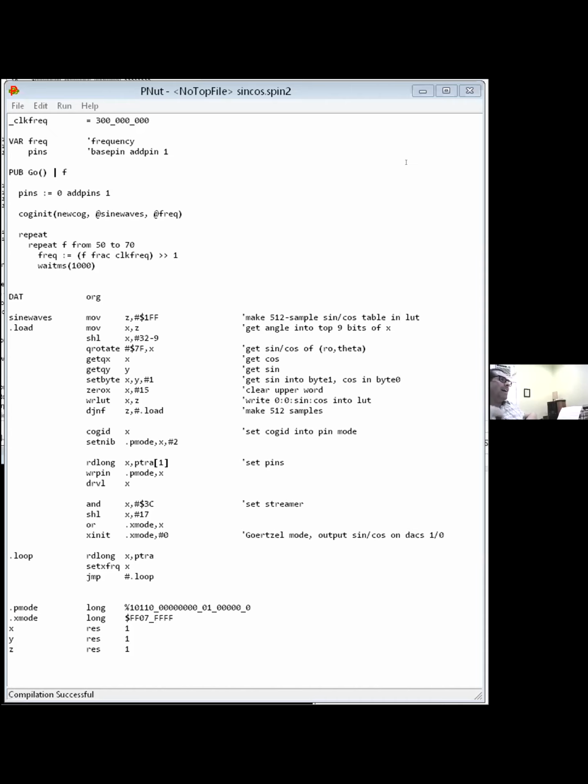The data is all going through these internal channels in the chip, and it's not really available for looking at. So we'd have to run the analog output into another pin and look at that using the ADC. Could be done. Yeah, you're just sampling it, so you get stair steps and stuff.